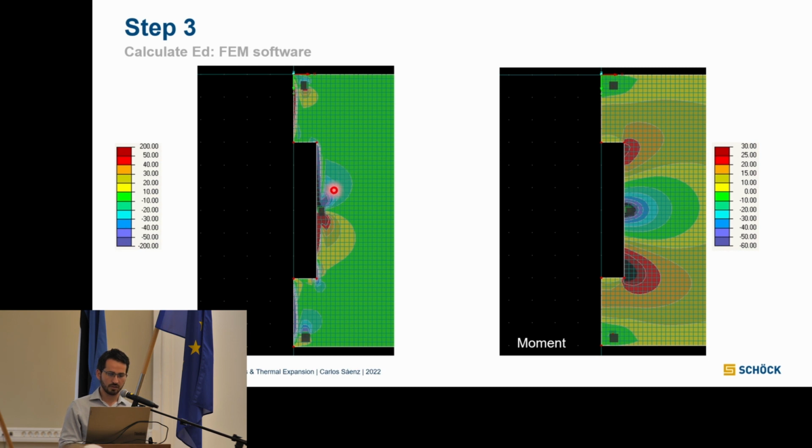And also really important, because you get to see we had a column here, if you remember. Now, if we do the design how it's supposed to be, we only have 3 faces for that column, for the punching shear that can occur around that column.